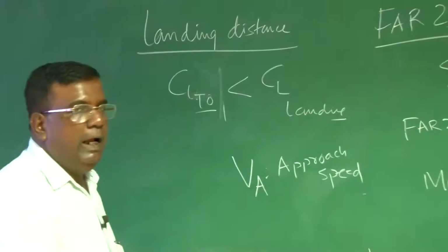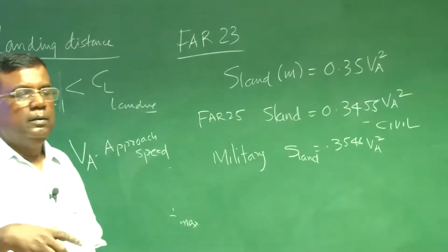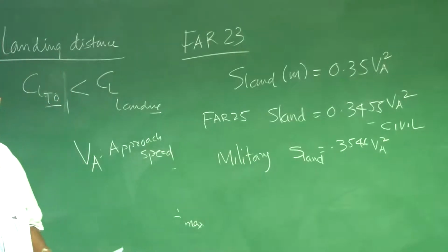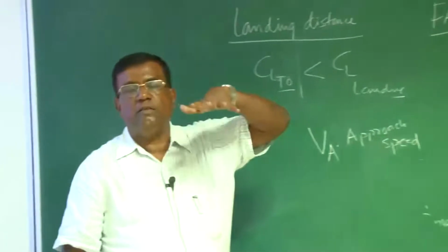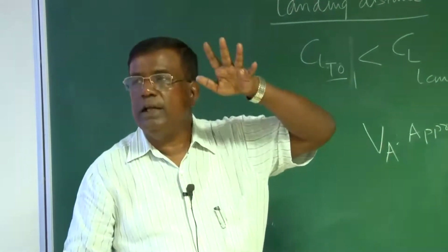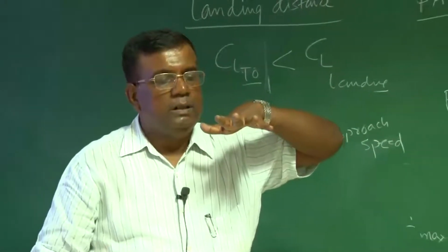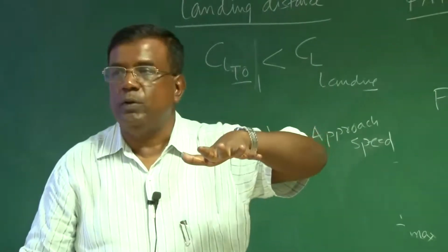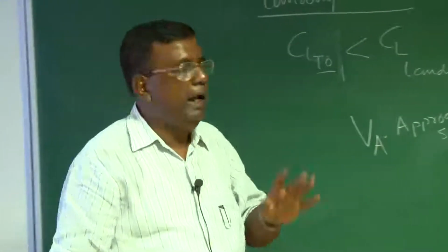See, when you want to land, you come to the point nearer to the airport, and you set a glide slope of 3 degrees, right? We talk to the ATC, say, okay, now start. So with a 3 degree glide slope, you start approaching the airstrip. Then you do the flare and land, whatever it is.